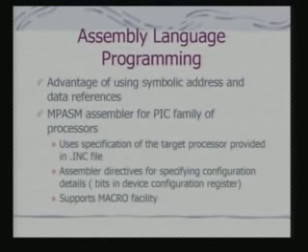But the assembler for PIC has to handle some other very interesting and important tasks, because PIC is not just a single processor, but a family of processors, and for that family there will be variations in a number of configurational issues, variations in the stack size, variations in the instruction length, variations in the availability of different peripherals on chip.